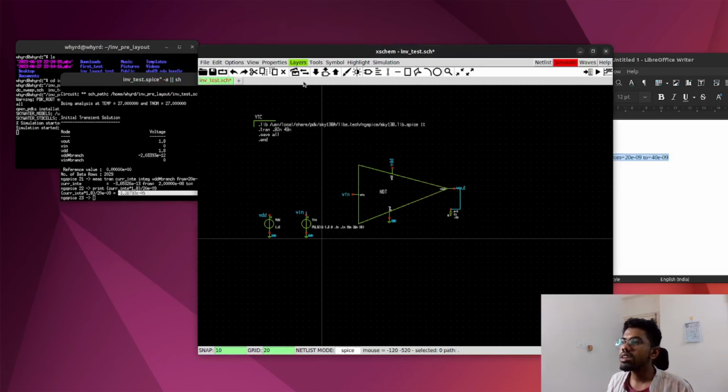And you can also see here, if we increase the size of our inverter, and why do we increase the size of our inverter? To speed things up. If you want speedy circuits, then you probably need to increase the size of this NMOS and PMOS, and if you increase, then your power again shoots up. So these two things go in different directions. An efficient circuit needs a bigger circuit size, but then again your power budget will increase. So there we need to maintain a balance. Actually, you can do this task: just increase the size of this inverter and see how your power jumps up.